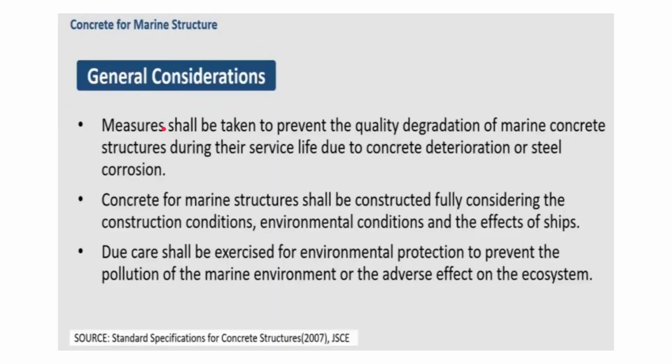General considerations: measures shall be taken to prevent the quality degradation of marine concrete structures during service life, due to concrete deterioration or steel corrosion. Concrete for marine structures shall be constructed fully considering the construction conditions, environmental conditions, and the effects of ships.